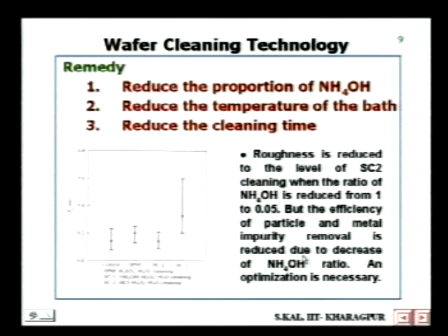So NH4OH basically removes the particles, but if you reduce its amount in the solution, it loses its efficiency for particle removal, and optimization is thus highly desirable.